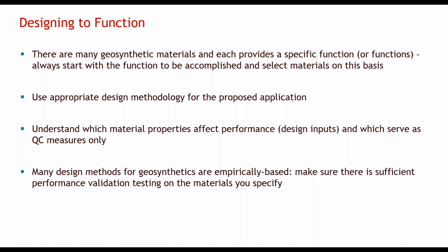In most cases, there are well-established design methods that are endorsed by independent authorities. These may need to be adapted for innovative materials, but you should always ensure that the underlying approach is valid. Similarly, make sure you understand which material properties affect performance. These will be design inputs, and which serve as quality control measures only. Most design methods for geosynthetics in roads are empirically based, so make sure there is sufficient performance validation testing on the materials you specify, and make sure that testing is reflected in the design method you're using.